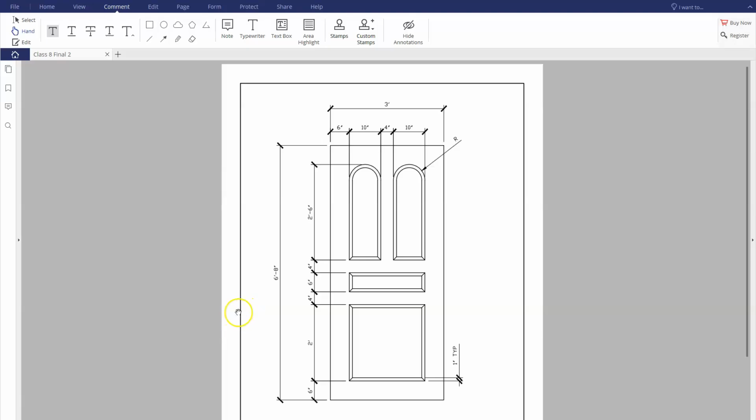Okay, so on this one, the first thing you need to notice is that all of you are in architectural units. That should tell us that we have to switch our units in AutoCAD so we can use these. Otherwise, you can just convert all of these to inches and run with it. But it's a lot easier, especially when you have 6'8", if you don't want to do the multiplication on it. So we're going to switch on over to AutoCAD, and I'll switch into architectural units, and then we should be able to build this one fairly simple.